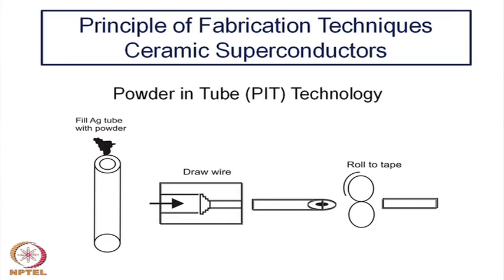So, it can be a soft chemistry route, it can be powder synthesis techniques, solid state synthesis techniques. Like if you are talking about yttrium barium copper oxide, you can take yttrium oxide, barium oxide and copper oxide, all of them powders, mix them together and heat at high temperature, normally in a controlled atmospheric condition. So, that is the powder preparation technique. One can also use sol gel techniques, co-precipitation techniques and combustion techniques and so on to make the powders.